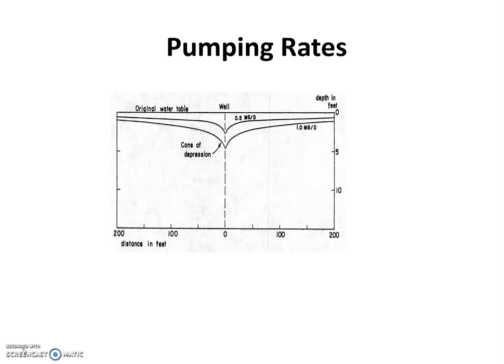And you'll notice that as the rate of pumping goes up from 0.2 million gallons all the way up through 1.0 million gallons, then the recharge area gets larger because more area is required to furnish that pumping rate. So what you're going to do in this lab exercise is calculate on a map what the radius of a circle will be for a recharge area at different pumping rates. So turn your attention please to page 35 and the map of Cliff Pond and the surrounding area.